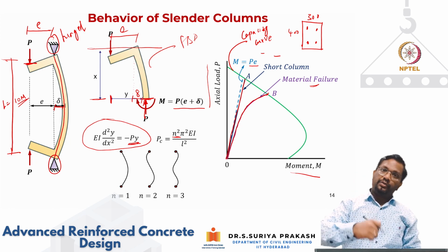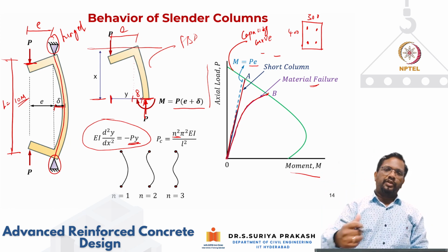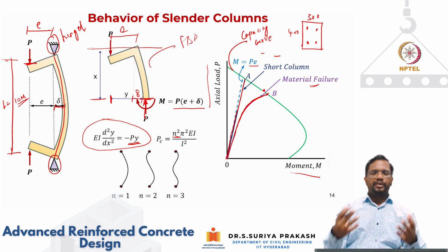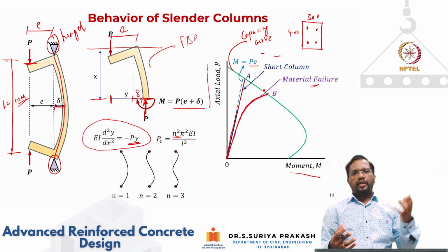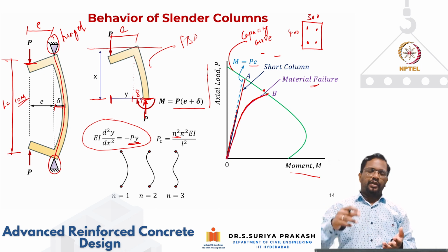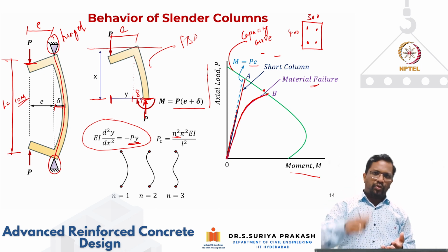Now the delta is going to increase. So the moment the delta increases, the curve becomes non-linear. Then you will have this kind of thing. As I go to more and more axial compression, the section becomes non-linear, or the elastic modulus and flexural rigidity of the section is going to decrease. That will induce more delta. Now, when I have more delta, again more moment.